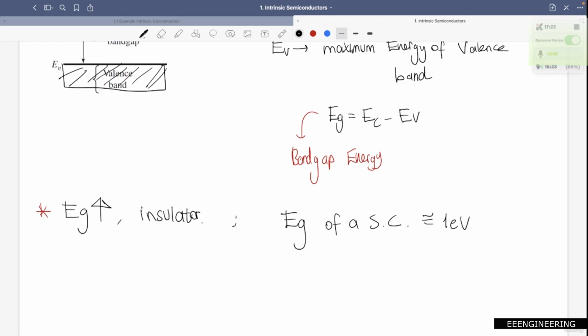So now with this information we are going to move forward with the concept of holes, which is really important. The net charge in a semiconductor is 0. That means our semiconductor is neutral. If an electron breaks free, it leaves its original position and leaves an empty space. That makes sense, right? This representation is not a good one, but it is a model, so I can do that. Let's say we have these 3 spaces, and each of them has an electron. If one of the electrons gains enough energy and breaks free of its bond, there will be an empty space right here.